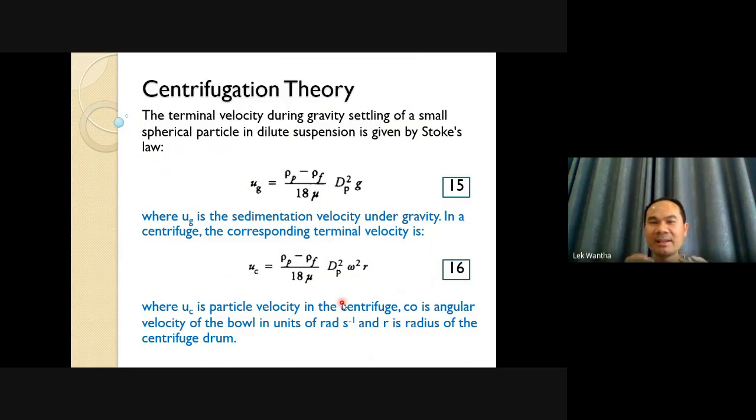This is the comparison between the force based on gravity and the force based on centrifugation. Please remember that in this technique we design the force to be greater than gravity. If the centrifugal force is less than gravity, more solid will drop to the bottom. But if the centrifugal force is greater than the gravity force, more solid will move to contact the surface of the wall and deposit there. This is the technique to separate by centrifugal force versus G force.